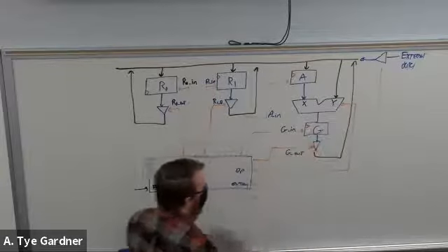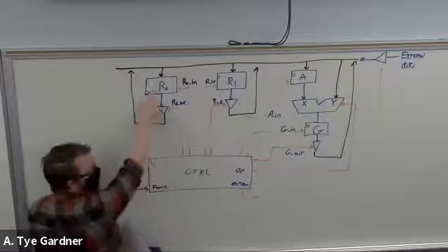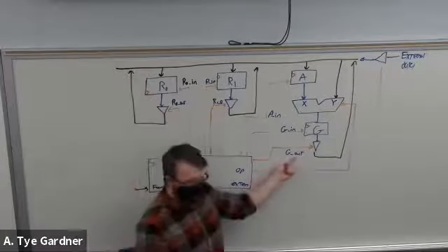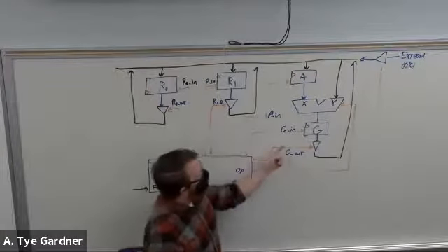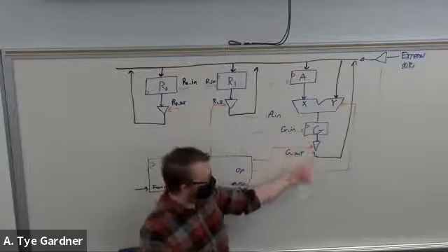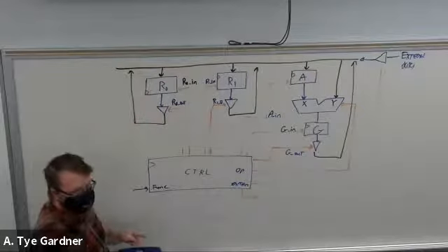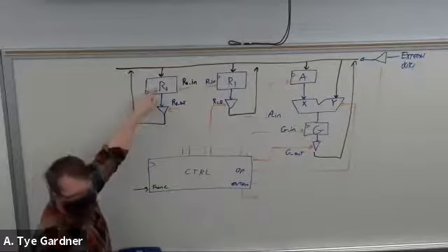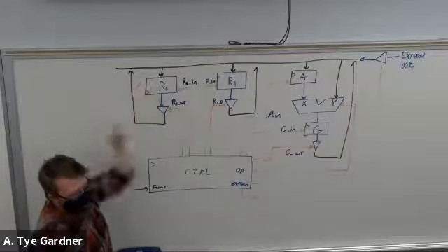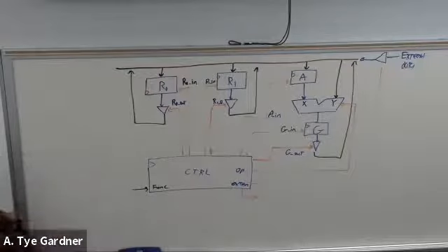Then on the next clock cycle, if I want to go back and store that, say I'm done with the 3s, well, I enable G out, making sure that all of my other enables, my drivers, are all off except for G out, and I turn on R0 in. So on the clock cycle, the 3 gets overwritten, and we store that 10. So that's how it works. That's the general idea of this bus.